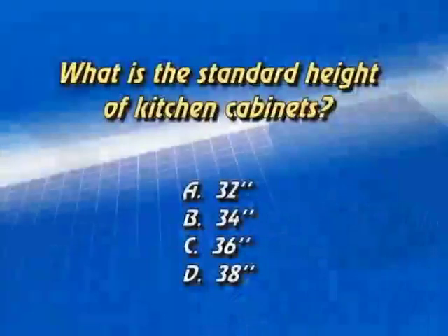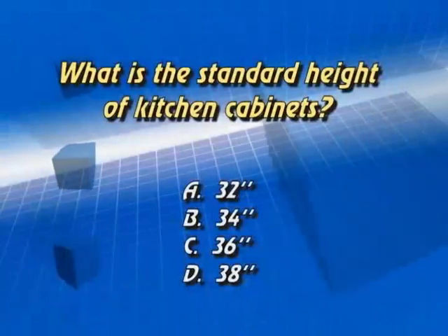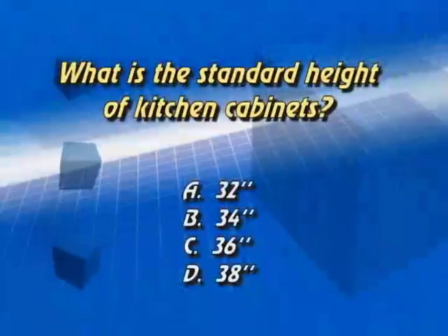Number 57. What is the standard depth of a base cabinet? Standard depth of a base cabinet is 24. Number 58. What is the standard height of kitchen cabinets? Now, the staff got together and we discussed this question. We finally figured out what the question is actually asking is, once the cabinet is completed with its countertop, what is the standard height? And of course that would be 36 inches. Without that countertop height, it's usually 34, 34 and a half. But figure on this question, we're asking about the finished height, with the countertop. Again, 36 inches.